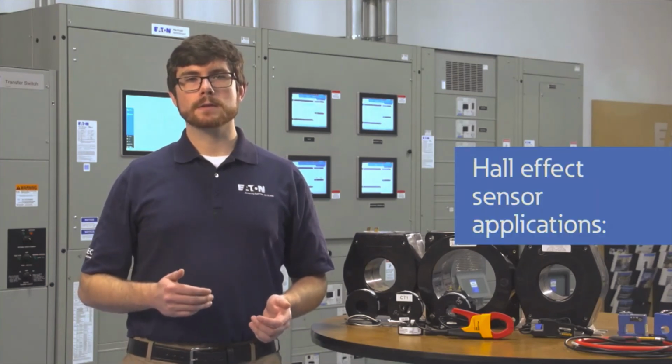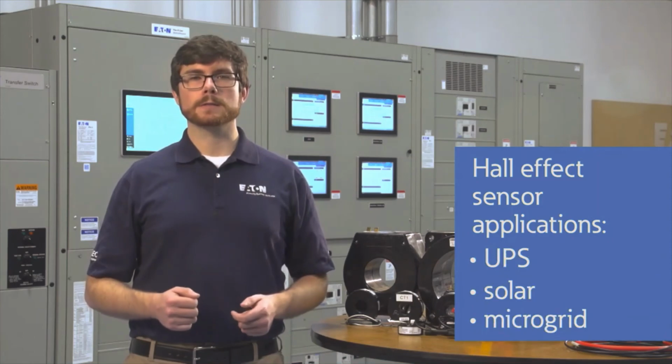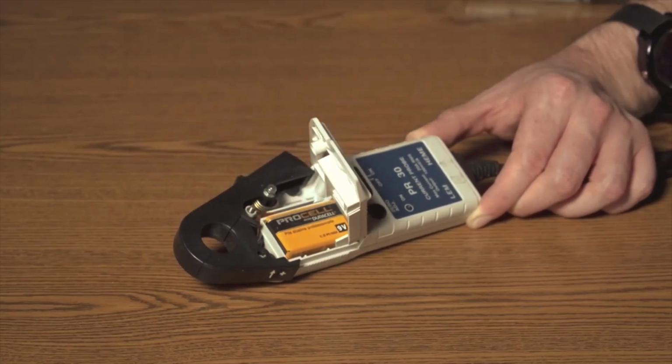Hall effect sensors are used extensively in UPS, solar, and microgrid applications for monitoring DC currents. A disadvantage of Hall effect sensors is that they require a DC voltage source in the form of a battery or fixed power supply. Drift can also be a potential problem, requiring them to be compensated periodically through a degaussing or calibration process. Many multimeters utilize a combination of CTs and Hall effect sensors in order to get an accurate current measurement.